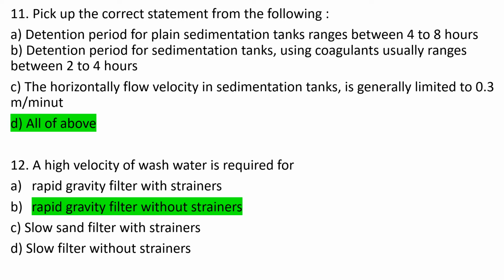Comparing rapid gravity filter and slow sand filter, rapid gravity filters require more wash water for cleaning. And comparing rapid gravity filter with strainers and without strainers, comparatively rapid gravity filter without strainers require more water. So the answer is B, rapid sand filter without strainers.